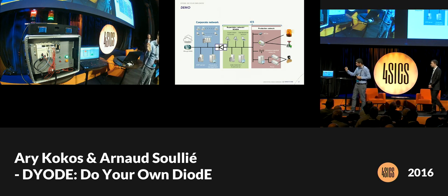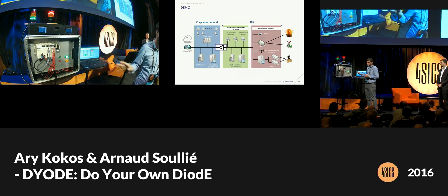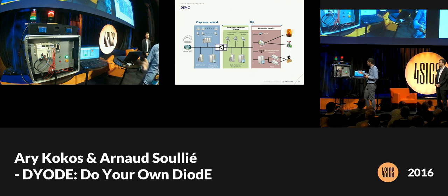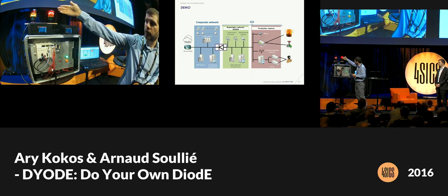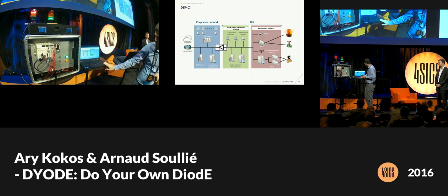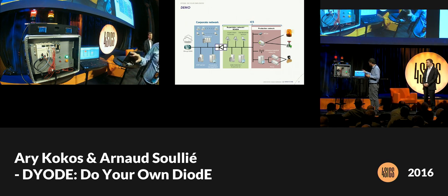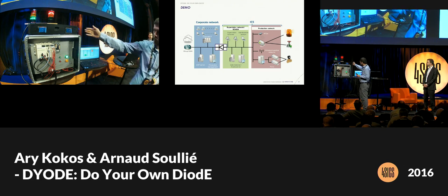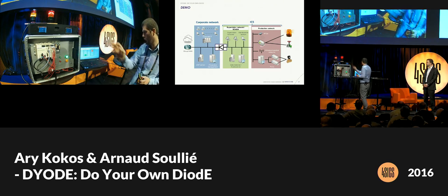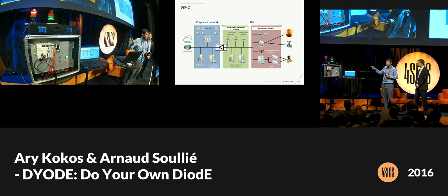So let me also introduce our little setup over here. It's really basic. The idea is to have some kind of traffic light control solution. Here you have two lights that are supposed to be traffic lights. They are controlled by a Schneider PLC. And we also have a SCADA system here. It's a real one, IGSS from Schneider also. They have a free version. So we use that to have real SCADA software in our environment. Then, again, here is our data diode, and my PC will be the corporate PC that will access data from the ICS.